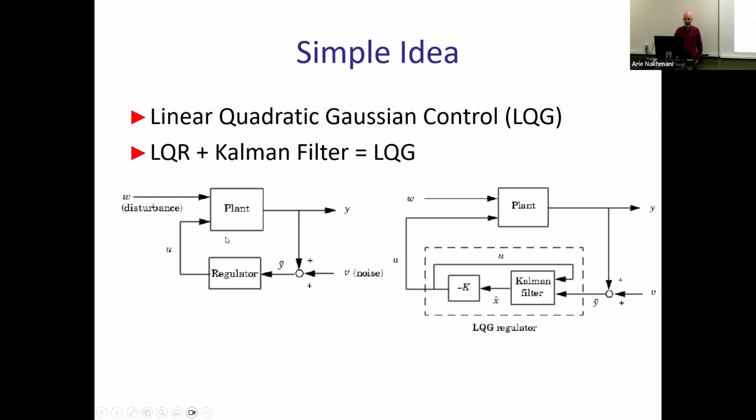But this regulator needs to read the input of the plant somehow from inside, okay? And also error, which means it needs to know what's the error between output and predicted output, and it needs to know the U part, which is control effort of the system, because this is what observers do, okay? And I want to write that, in that case, as transfer function also, okay? So instead of writing that as just K and L vectors, I want the actual transfer function of the controller to get it back to the form that I'm used to see in controls one type of courses, okay?